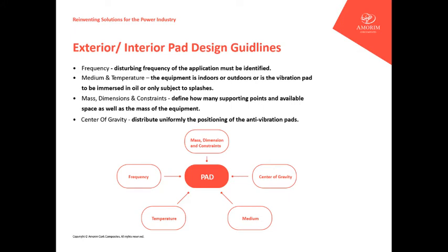an efficient solution. It's also important to refer that this solution is under compression. So we are talking about pads that will be under compression, and it's very important to know that to take the max benefit of this solution, the pads should be compressed between 5 and 20% compression.